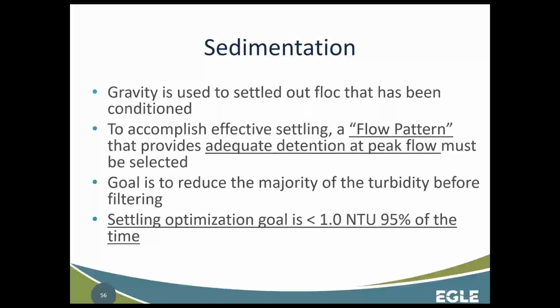Just as a quick plug for the AWOP program, I look at it to some extent as compliance insurance. If you're meeting those AWOP goals, then you're going above and beyond what's required by the regulations. Also, by tracking this information, and for those of you who have seen the graphs and data produced out of their workbooks, you can really get a sense. Maybe you've got two settling basins and you realize one is outperforming the other, and it might lead you to make adjustments to your process to increase the effectiveness of one of the basins.